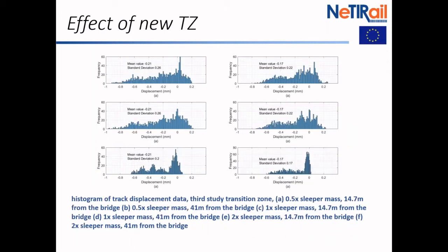So in terms of installing this, you would have a much, much cheaper installation to just make a normal embankment and use the double mass sleepers. And that looks like a very good way of making a low-cost transition zone and reducing displacement without all that construction. The data is quite hard to see in that graph.